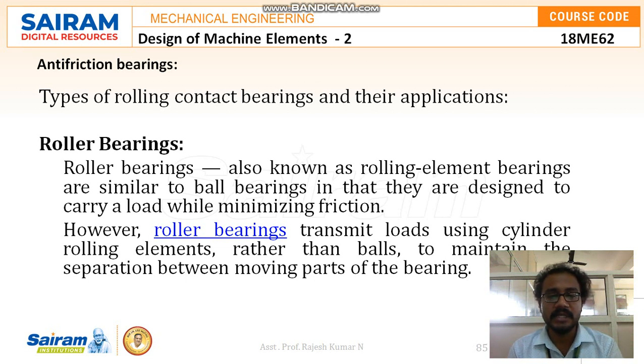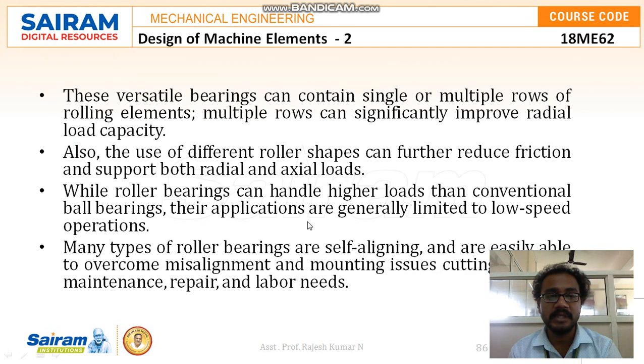Roller bearings, also known as rolling element bearings, are similar to ball bearings in that they are designed to carry a load while minimizing friction. However, roller bearings transmit loads using cylindrical rolling elements rather than balls to maintain the separation between moving parts of the bearing. In some industrial machines where this is recommended, instead of going with the general solid bearings, roller bearings can be seen.